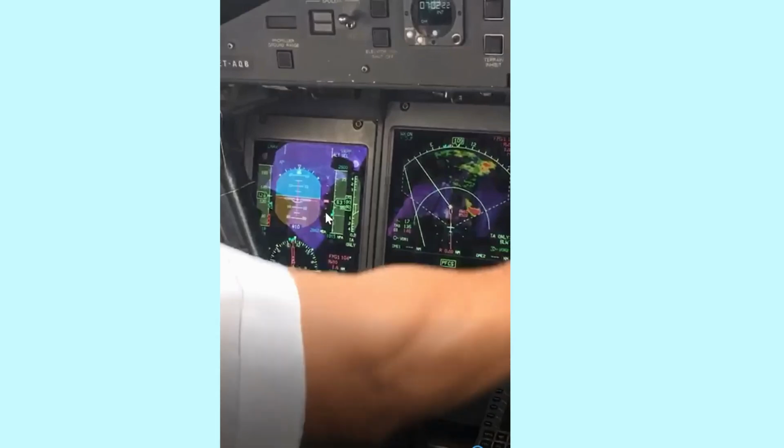And you can clearly see right now the autopilot itself is keeping the pitch in between there. So we don't have to change anything. Unless something comes up, then definitely we can, but otherwise you can see that this is a good reference compared to having to scan the small digits, which some people can do with experience and more practice. You can actually even glance these numbers here, but this would be a very good visual cue that your rate of descent is exactly what it has to be for a particular approach.